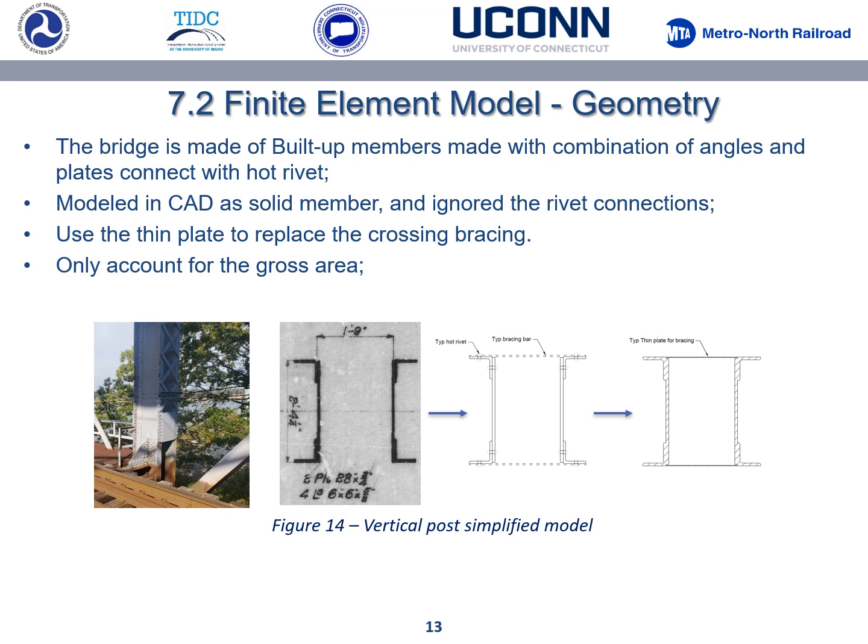That's the modeling process. The four figures from left to right show the modeling process. We have the plates and angles, then there are some cross bracing. So the first thing, we dig into the drawings, we extract the cross sections, and we model using the right cross sections: the angles, the plates, all those things. Eventually we combine everything and replace the cross bracing with a thin plate, I believe it was 1/16 of an inch, and from there we extrude. That slightly changed the cross-section properties, but we tried to minimize that change using that process.